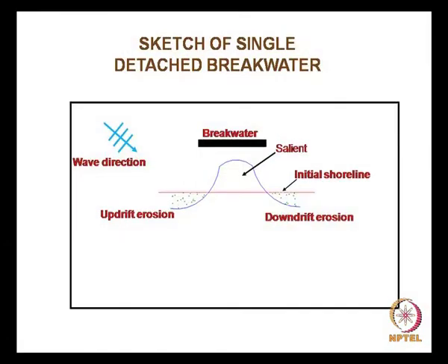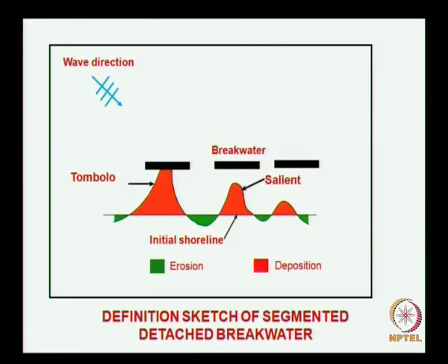When you have a single detached breakwater, we have already seen during the introduction, under the phenomenon of diffraction, that the wave climate between the shoreline and the breakwater is going to be very calm compared to the adjoining areas. Hence the sand comes from higher energy to lower energy, that is, on the lee side of the breakwater you will start getting the buildup of the beach.